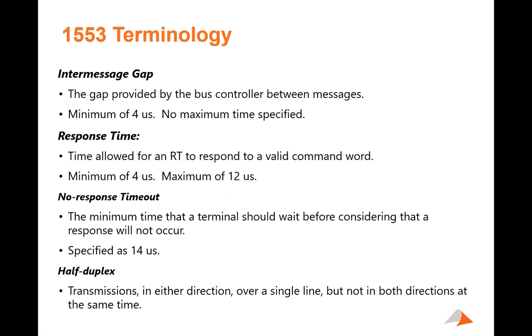Response time. This, of course, is like if you're sending the message to the RT and it's going to send back a status word. It's got to send it back 12 microseconds at the most after it received it, because it means that on a long bus that the bus controller is going to see it at 14 microseconds. And so a lot of people, in order to keep their buses snappy, will set them up at 6 microsecond response times. And just keep in mind that the bus length does have something to do with the total time.